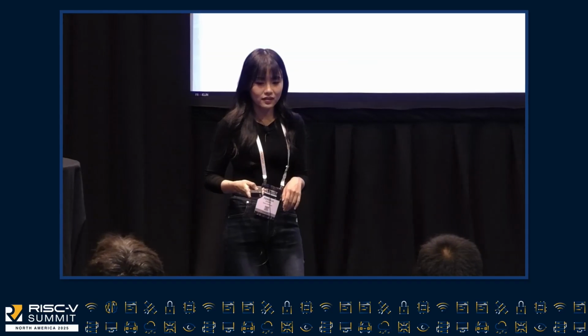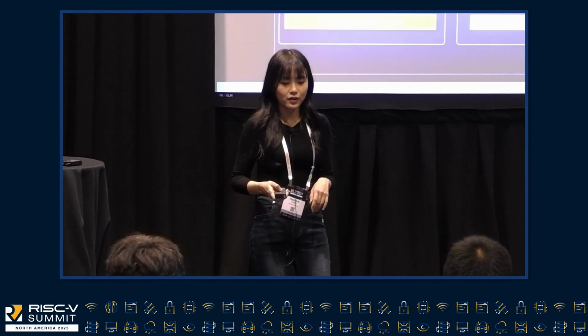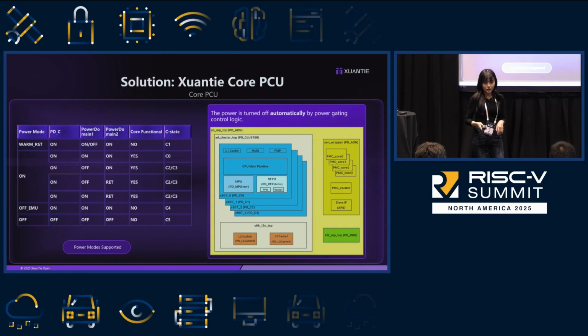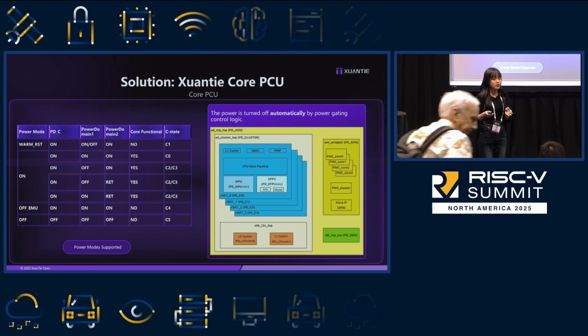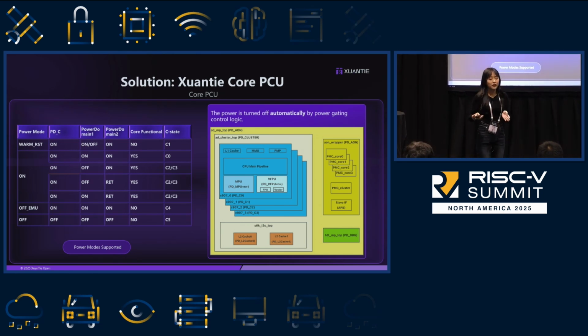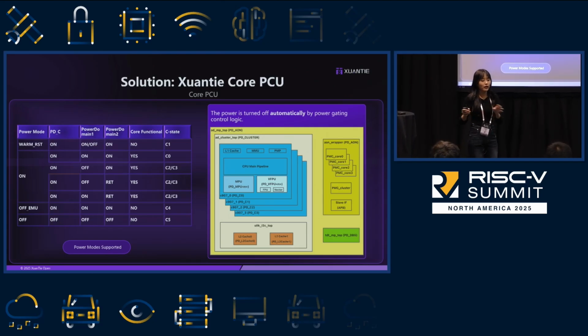You mean the slides over here, the different types of CPU modes? Yeah, the previous slide. This one is not used in the CPU standby, but we use it in the CPU suspend in the running state. The power modes are to be set before the core goes to WFI. So we have different types of flags to be set.